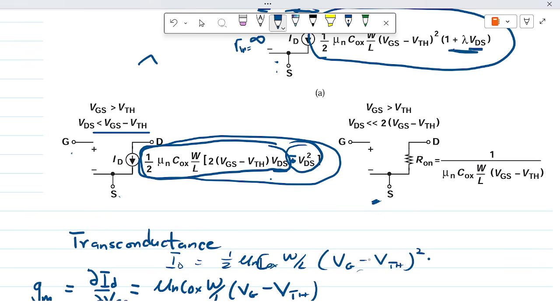When you plot the curve, we are looking at the beginning part, which approximately depends on this side of the equation. You may be used to putting this inside and canceling these two, and it's the same thing. When you write it that way, you can model that part when VDS is really small, smaller than twice the overdrive voltage VGS minus VTH.